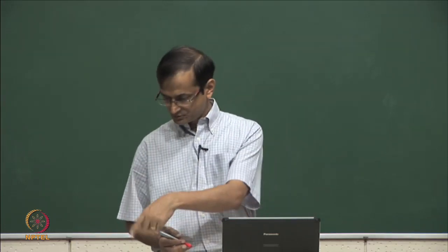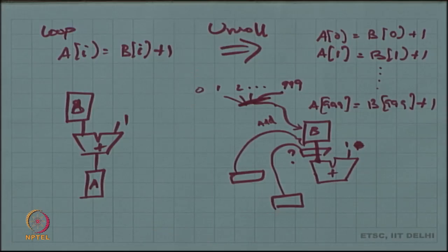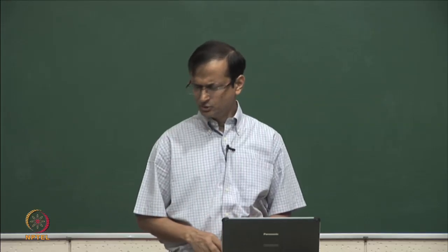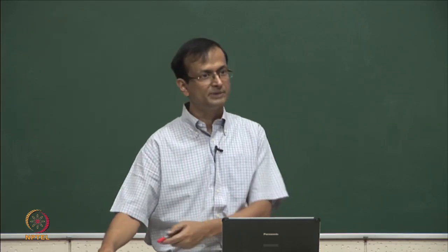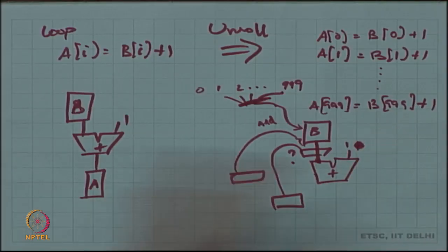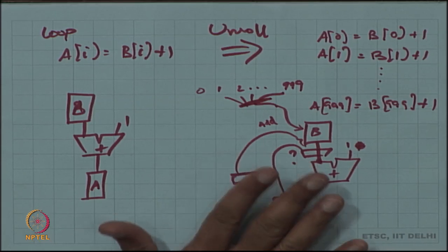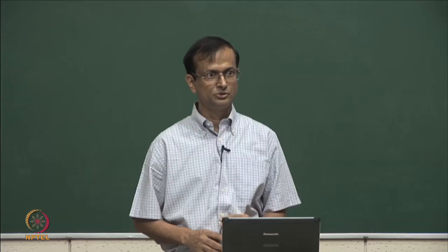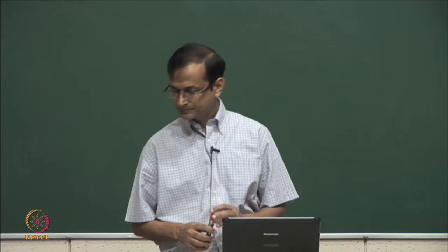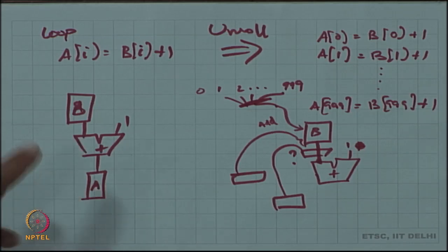If I proceed in this straightforward way, there is that mux, such muxing might actually show up as a bottleneck. You do not have to, of course, you know that there is a better way to design this. It is just that at this extreme, it seems as though it is not a good design. Have a counter and loop over. Remember that hierarchical design that we did, where we nested the loop and we said that the inner loop is what would be unrolled. That could possibly lead to a difference. The implication of that I plus plus is a counter.